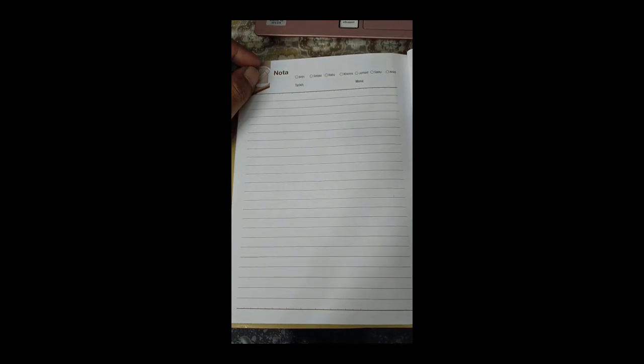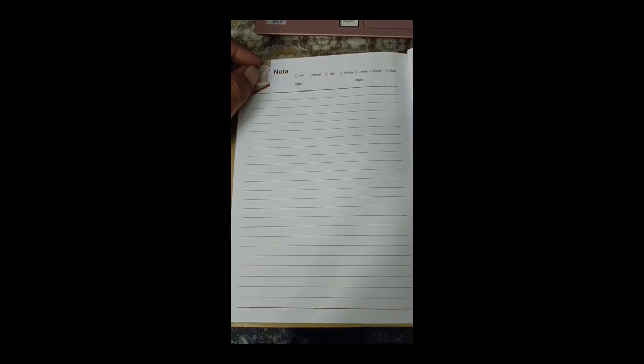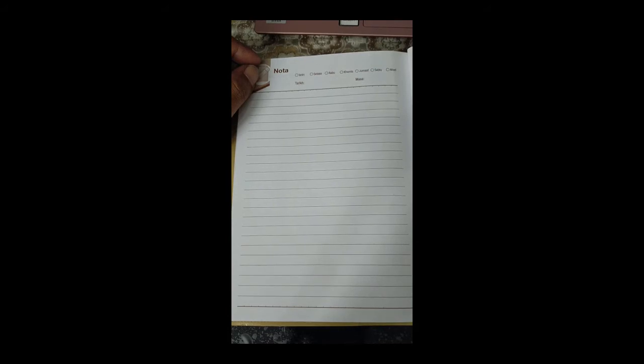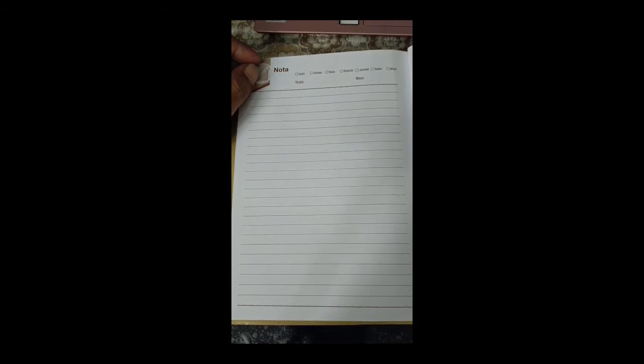Inlet, given directly: the pressure 2 MPa, temperature 400 degrees Celsius, velocity 50 meter per second, and Z, the potential energy, is 10 meters, while the exit is pressure 15 kPa, X fraction is 90%, velocity is 180 meter per second, and the Z, the height, 6 meter.